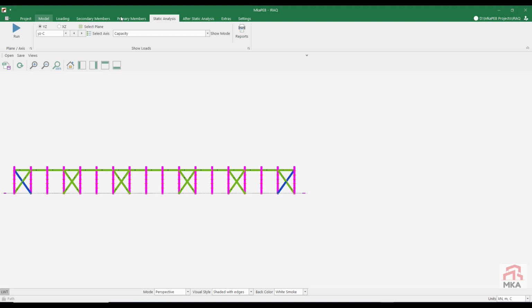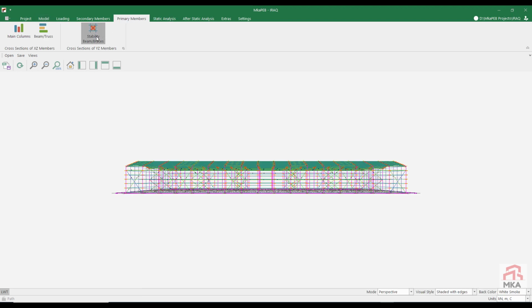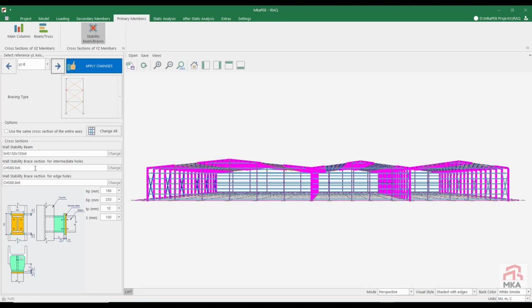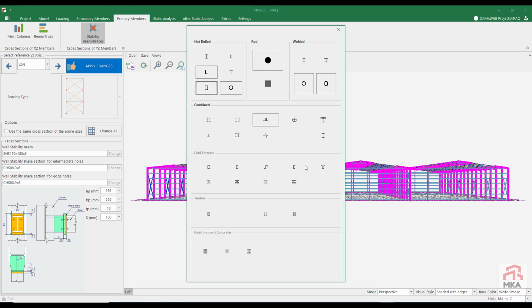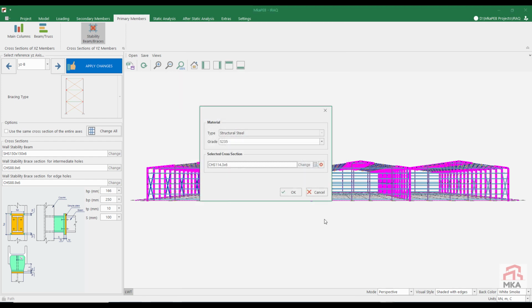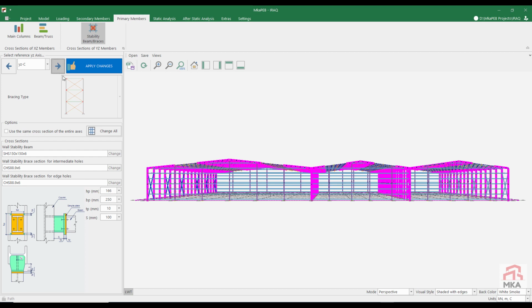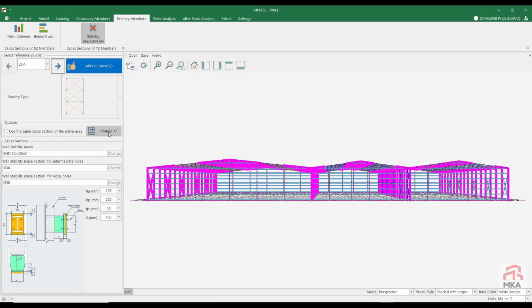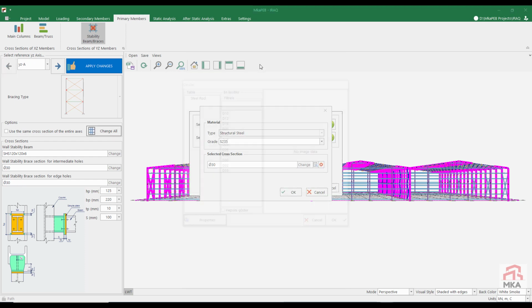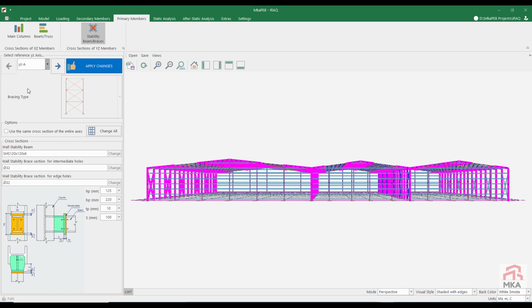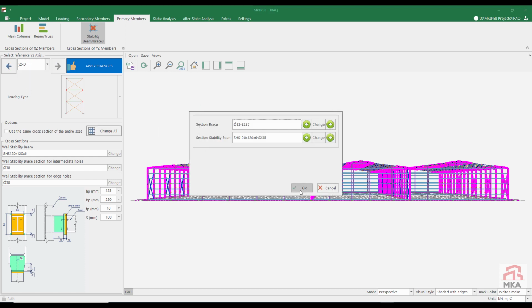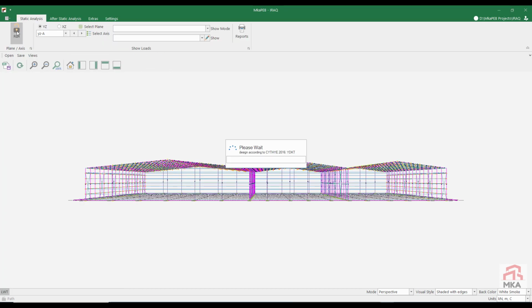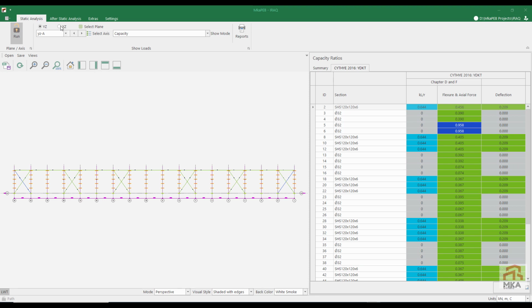Let's show you how to swap first and last row bracing cross sections. In YZB and C axis we try to use CHS 114/6 instead of CHS 89/6. In YZA and E axis, I want to try D32 instead of D30. After this stage, we will do the static analysis and we will finish our project by looking at the total cost of the building. The results are slightly better.